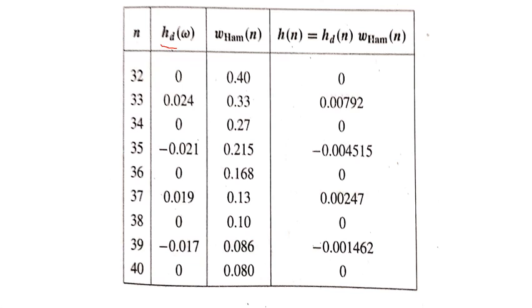While computing the value of hd of n, kindly bear in mind the value for hd of n for n equals 20 is already computed in step 6. Therefore, you use that value in this table. Similarly, you tabulate value of hd of n, the window function, and h of n for value of small n from 0 to 40, and this concludes the numerical.